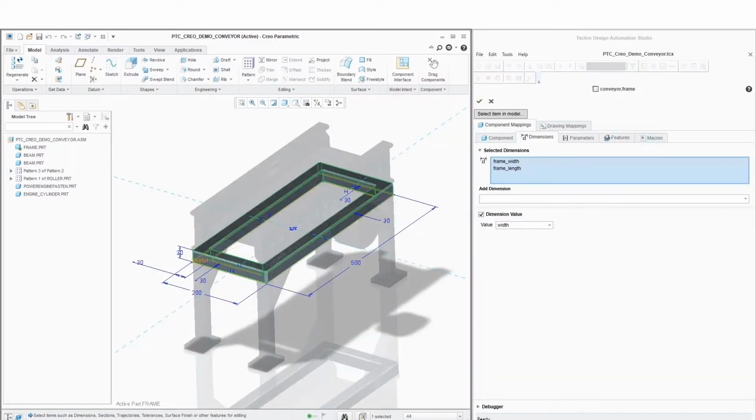So this is the mapping tool. This is where you create the connection between the CAD model and the Tacton model, and you can show the dimensions in Creo, and that lets you point and click on the dimensions to create the connection. So we have an easy point and click functionality, but we also have a filter list that filters or shows all the correct objects for this specific mapped component. I will go through this as well during the demo.